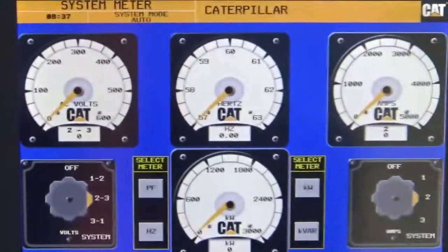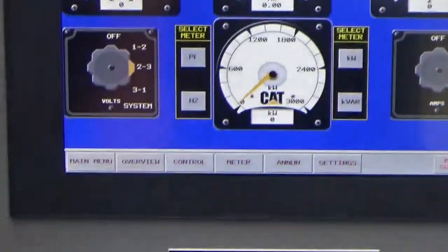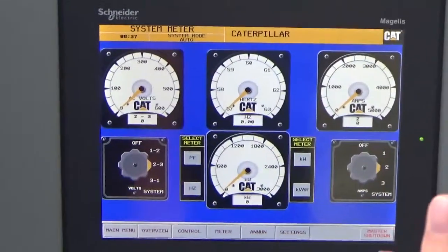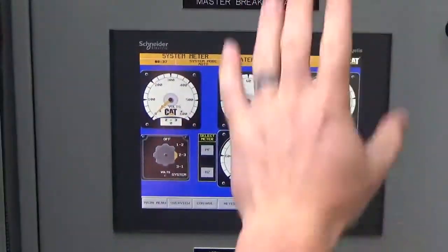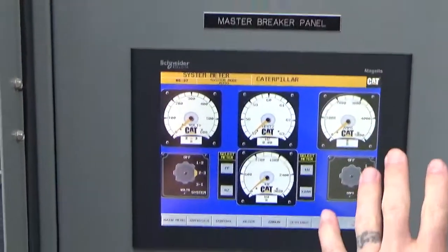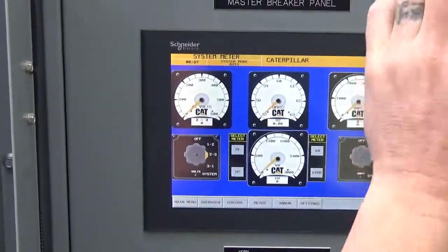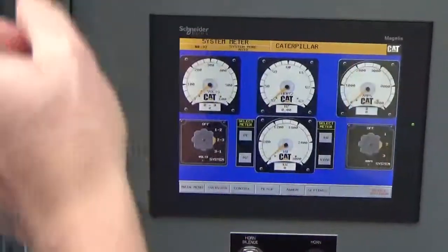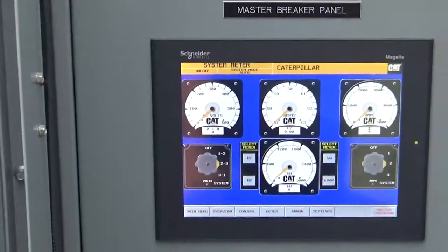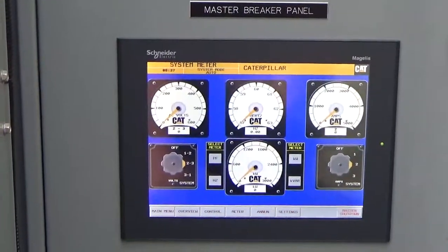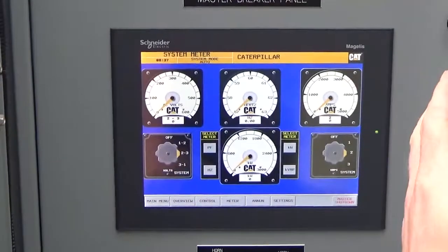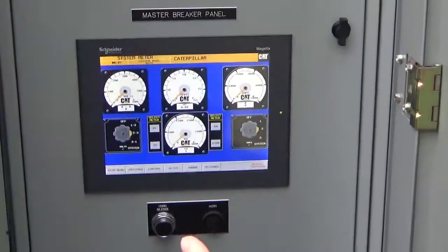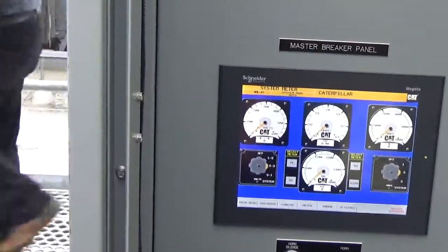Now the way it works is when it comes to those electrical safety alarms, we want to trip here first. This is your first point of failure. You want here to trip first. If this fails and somehow the breakers are not tripping, then it goes next down the line. It just keeps working down, because you want to try to avoid damaging equipment. So you want to do it here first, where the equipment is probably a little less expensive than damaging a generator, where the equipment's a lot more expensive.